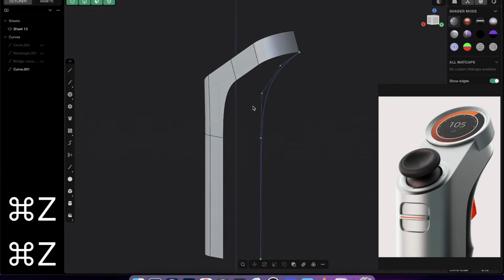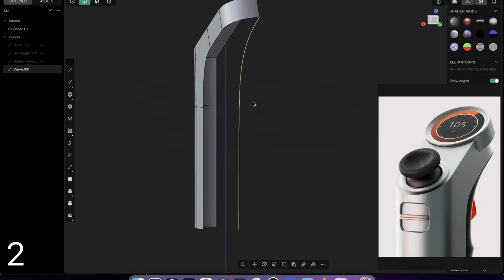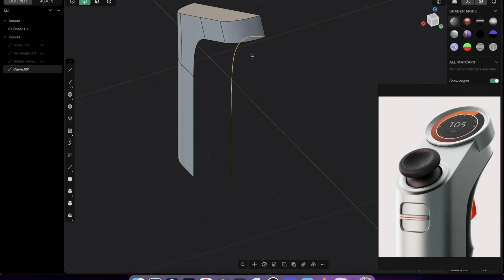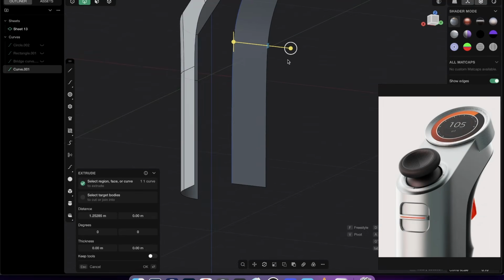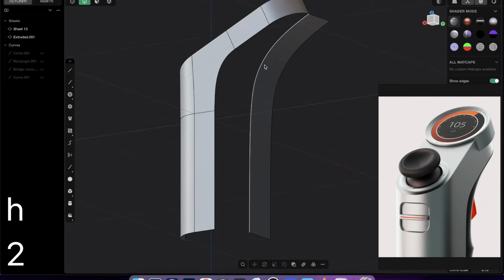And always before you do that, you always need the supporting surface first. So especially when you want to connect something in the middle as we have it here. So select the curve, press E for extrude and just extrude this a little bit. Does not matter how long. Now, also very important, press 2 and select the curve. So you have to select the blue curve first and hide it. So just make sure that this edge looks black and not blue.